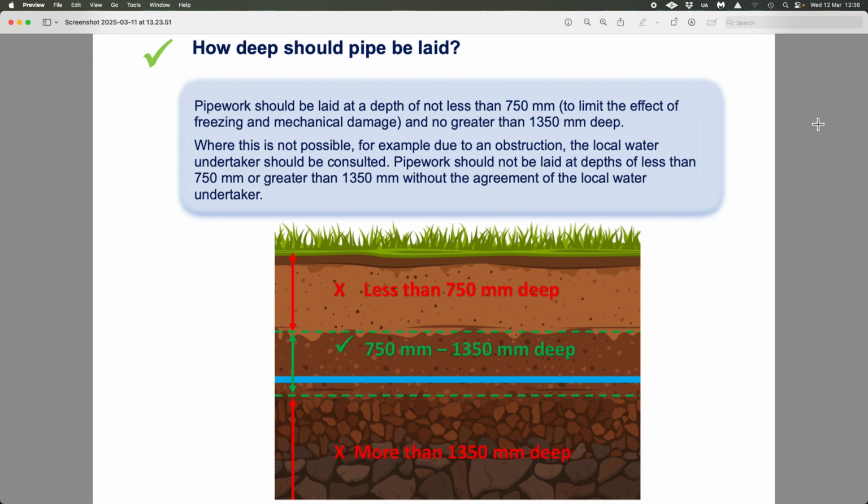So it's really important to stick to this 1 metre deep so you can maintain that 10 degrees of incoming water temperature, 10 or 11 degrees of incoming water temperature. And of course, that is well underneath any microbial growth scenarios of 20 degrees centigrade. But buried shallow, and I say I've seen water mains, even by water suppliers, that are literally just under the pavement, so less than 100 millimetres or 150 millimetres deep underneath the final ground finished surface, which is clearly not acceptable, and that's causing downstream issues.